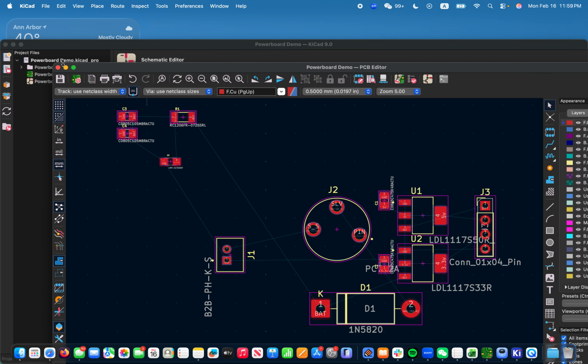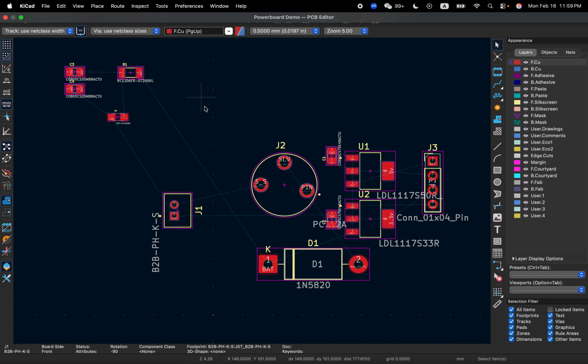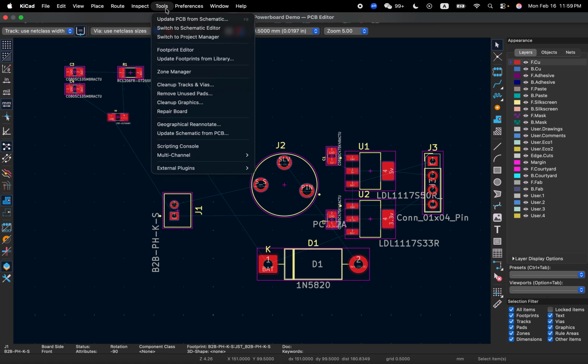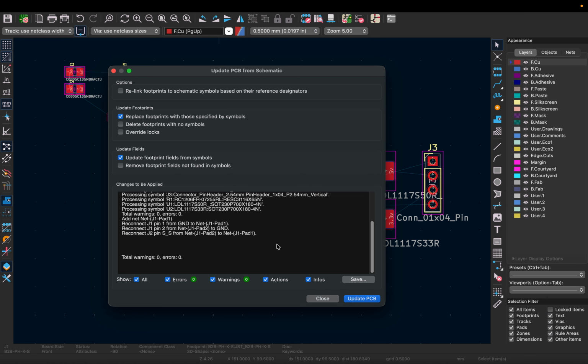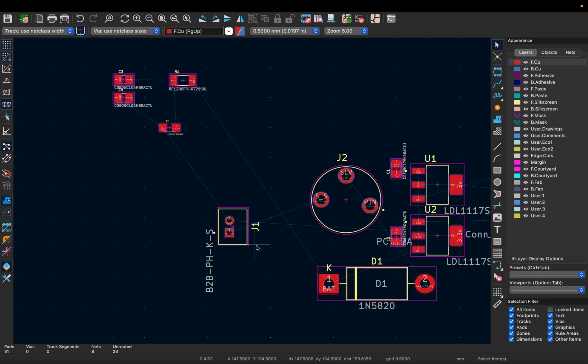So what's actually going to happen is, if you go into your PCB editor again, okay, let's remember the orientation here, and then let's go to Tools, Update PCB, and update and close. You can see, hey, now those lines are reverted while nothing else has changed because we didn't change anything else on the schematic. So that's how you can go back and fix one of your silly mistakes that you might make. Everyone makes silly mistakes.